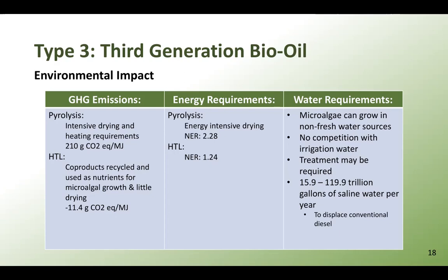As for the energy requirements, pyrolysis is definitely more than hydrothermal liquefaction. The NER was found to be 2.28, whereas the hydrothermal liquefaction was only found to be 1.24. They are both larger than 1, which is undesirable. As for the water requirements, it has intensive water requirements due to mainly the cultivation and harvesting stages, which are very water demanding. It was found that around 15.9 to around 120 trillion gallons of water is required per year to displace conventional diesel, basically, in order to produce bio-oil.